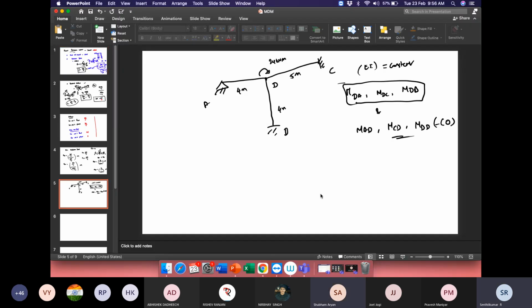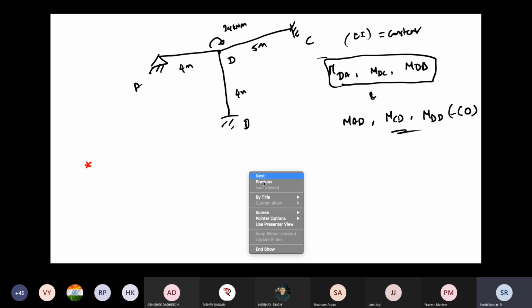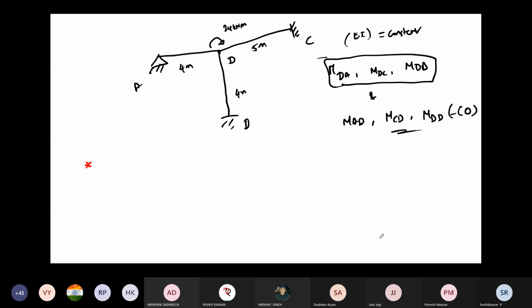Yes, sir. In proportion to stiffness factor, we will distribute. Yeah. So what is your first step? You have to distribute based on your stiffness, right? So what is your first step? You have to find out KDA, stiffness of KDB and KDC.